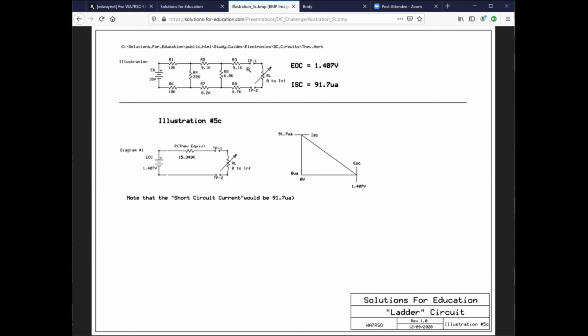How so? Well, because this dead short means these two resistors are in series with each other, parallel with this, in series with these, parallel with this, in series with these, and got it. Now I got all the resistance. However, now I know I have to go backwards. Now I say, okay, current flow, voltage division, current flow, voltage division, current division, voltage division, until I finally get back here. Now I can figure out what current will flow in that resistor or that dead short.